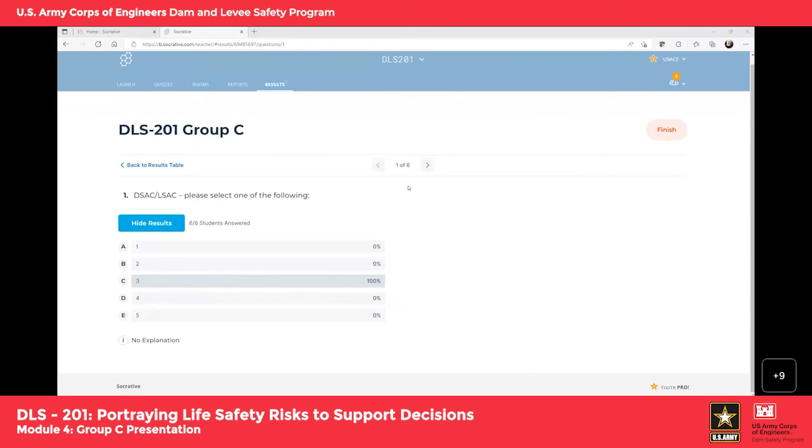So you look at both. You look at the total risk and it plots above the guideline, but you do have to give consideration to the big FN as well, because the little FN sometimes isn't the best vehicle to communicate risk when you have two wildly different PFMs.